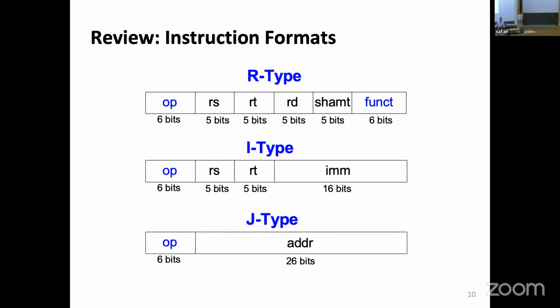Store word is the same kind of operation. It's the opposite. Whatever I have in the register will be written into that memory address. And we realize it has a similar I-type format. I have 2 registers, here RS and RT, and I have a constant. Now, this looks like showing my ear like this, and it is in a sense.